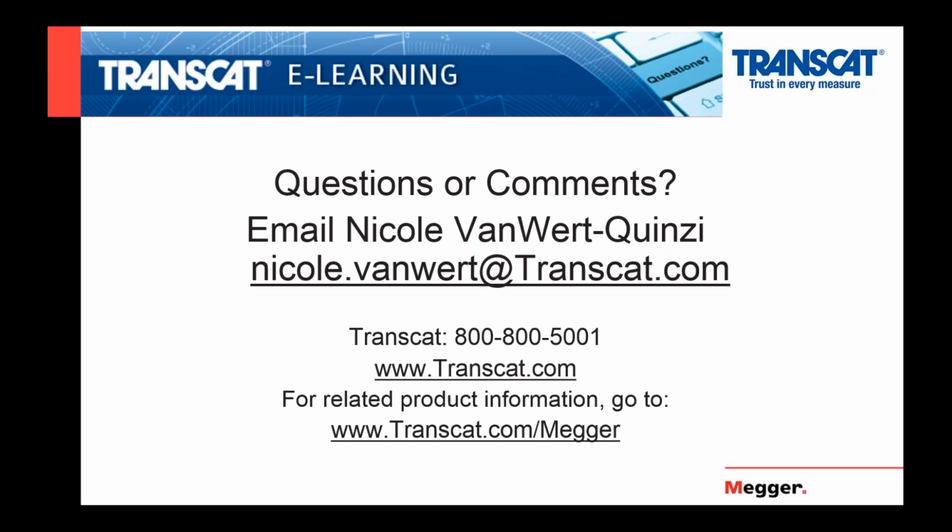If you have a VLA battery, a vented lead acid battery, typically if you just leave them on charge several days, a week or so, they're going to have full formation. And I guess I should explain what formation is. I really sort of skipped right over that, didn't I? When a secondary battery is made, as I said in the beginning, it's not charged. It requires a secondary operation to charge it.